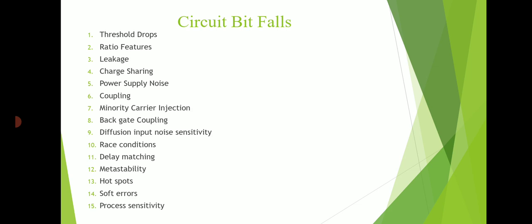And the major problem which occurs here is the leakage. To avoid this leakage, we are charging the node, and eventually this subthreshold leakage may disturb the charge. Finally it periodically refreshes the node, and also it requires a fast process. Based on this the leakages can be avoided. If you are holding the dynamic node as a charge node, then the subthreshold leakage may disturb the other charges. So this is one of the major problems. This leakage problem should be avoided, and hence the reliability should be sustained in the circuit.